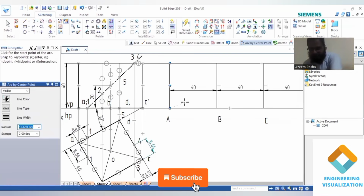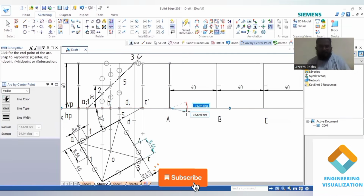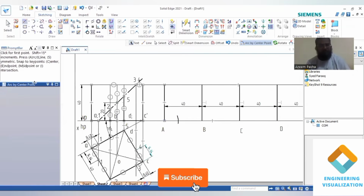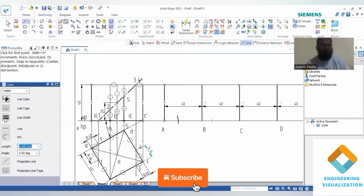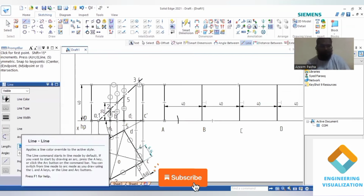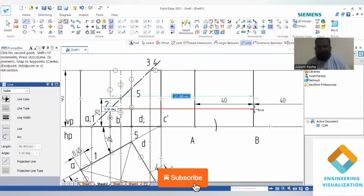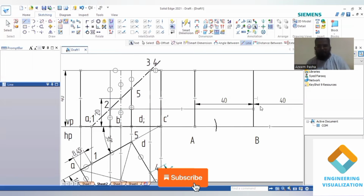I'll be measuring the length of 14.64 and cutting the arc. So cutting the arc, this is your point number 1. Now point number 2, we're getting exactly on the vertical edge B here. So for that I'll be drawing a horizontal line, till here B. So this is the point number 2.